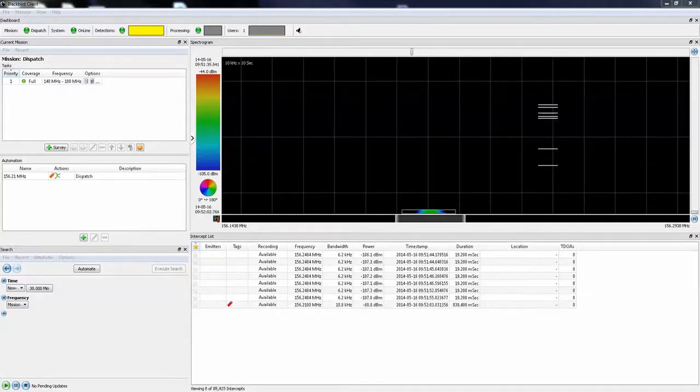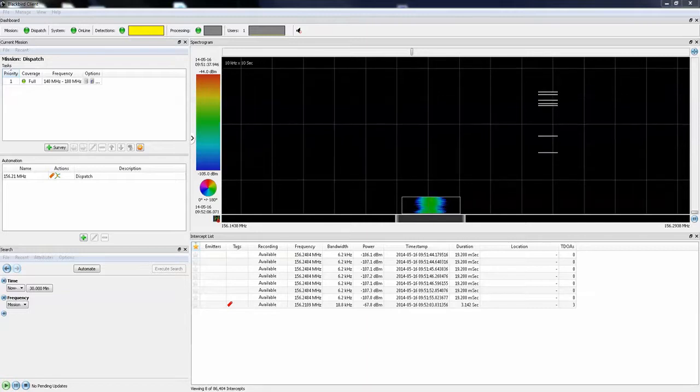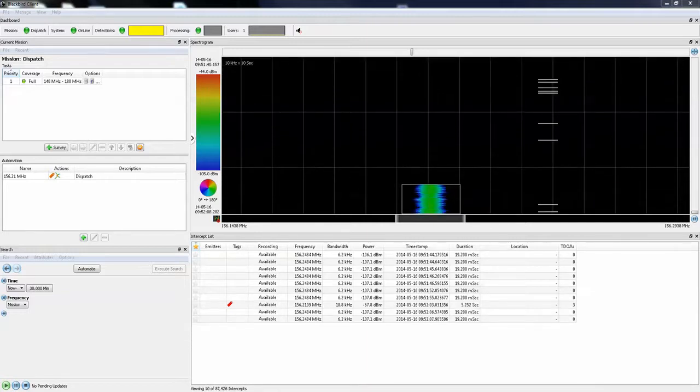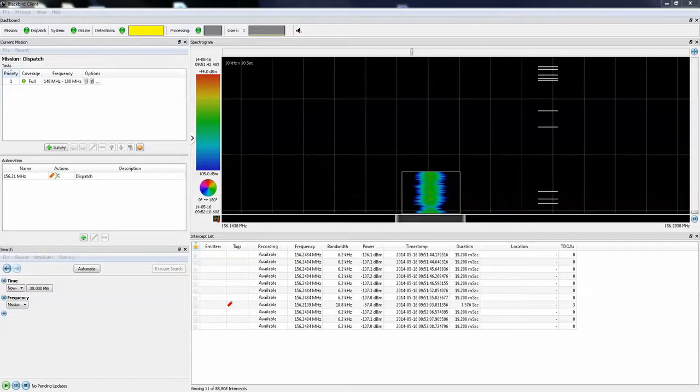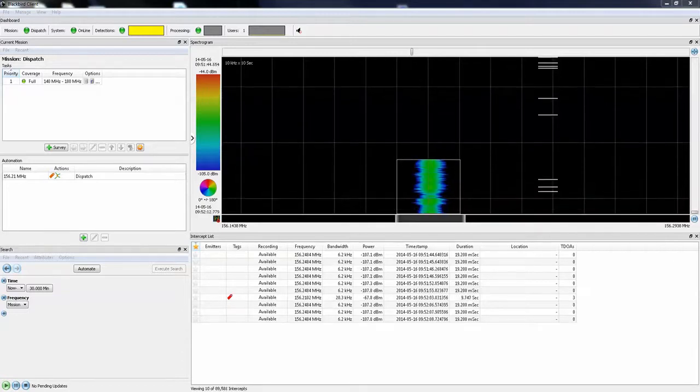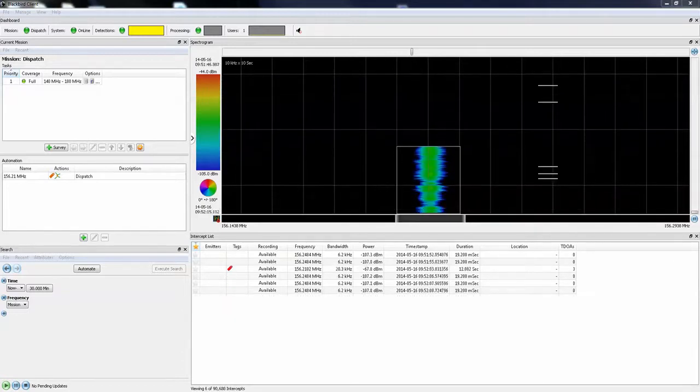In this last set of examples, we're looking at a series of aperiodic short-duration narrowband analog voice signals. Each transmission is detected and catalogued, and lookback TDOA measurements are automatically scheduled on each detected signal of interest.